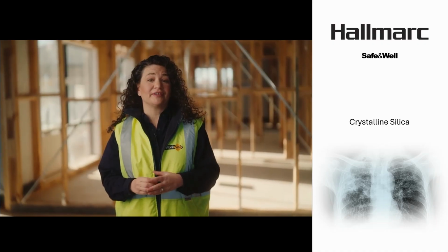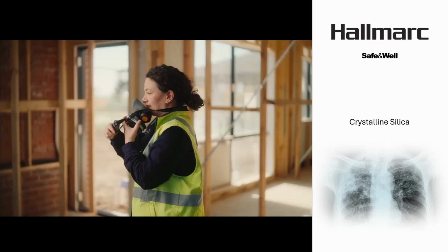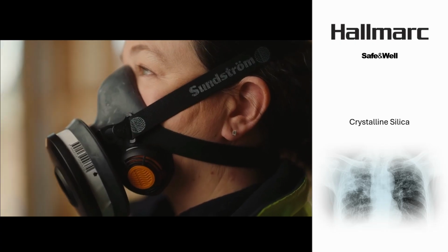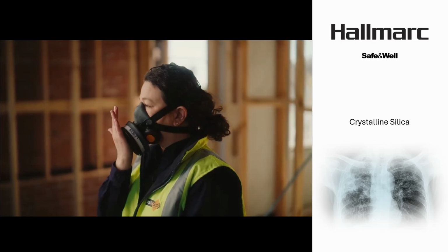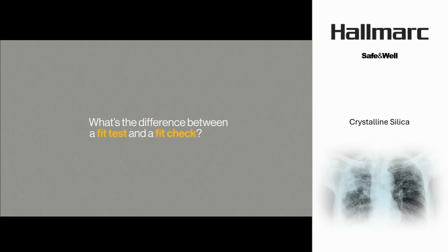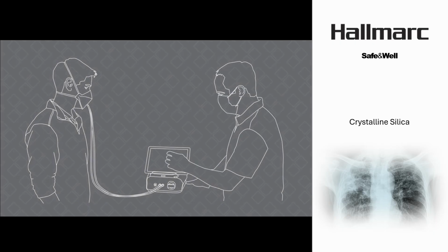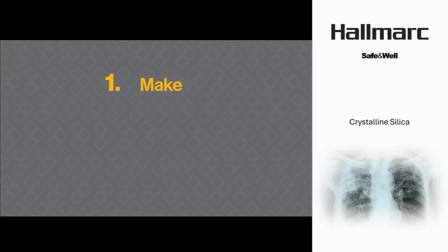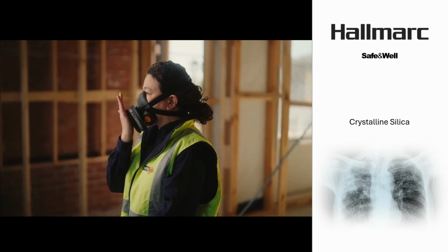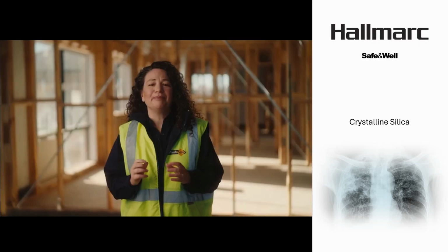For tight-fitting respirators, there's no one-size-fits-all due to the differences in everyone's facial features. This is why fit testing is a good way to confirm which respirator is suitable for each person. A fit check, on the other hand, should be done each time before using a tight-fitting respirator. So what's the difference between a fit test and a fit check? A fit test is done by a competent person to verify that the make, model, and size of the respirator is right for the user. A fit check is a self-check the user will do each time they use the respirator.